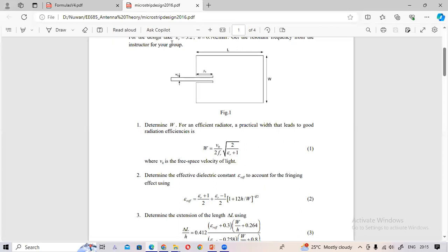This is the X direction. So if you consider your origin is here, this is Y equal to 0 and this is Y equal to Y0. So this Y equal to 0 is the impedance you are asked to match. So that will be 50 ohm, or the given ohm, maybe 150. And here the impedance is the input impedance of the antenna.